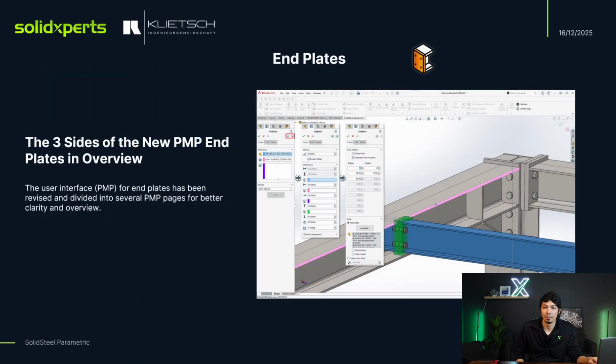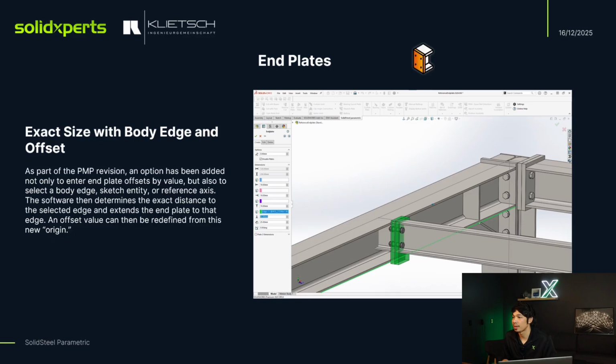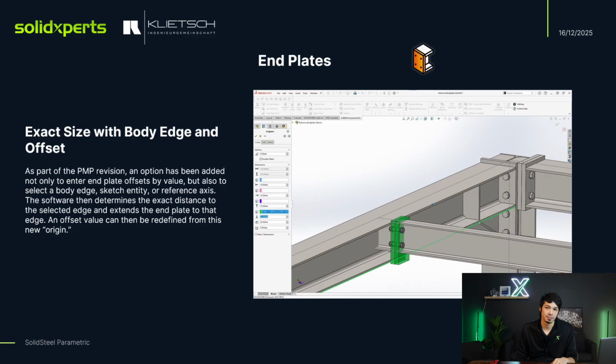Next up, we do have some improvements on our other features, like our end plates. When you're inserting an end plate into your model now, the end plate interface is divided into multiple property manager pages for clarity and easier navigation. Not only that, but we also have some new options that allow better selections. You can select a body edge, a sketch element, or an axis. The software will automatically calculate the exact length to that reference, and then you can apply an offset from that new baseline. This is something that will allow some extremely precise control over your plate length and orientation of that plate.